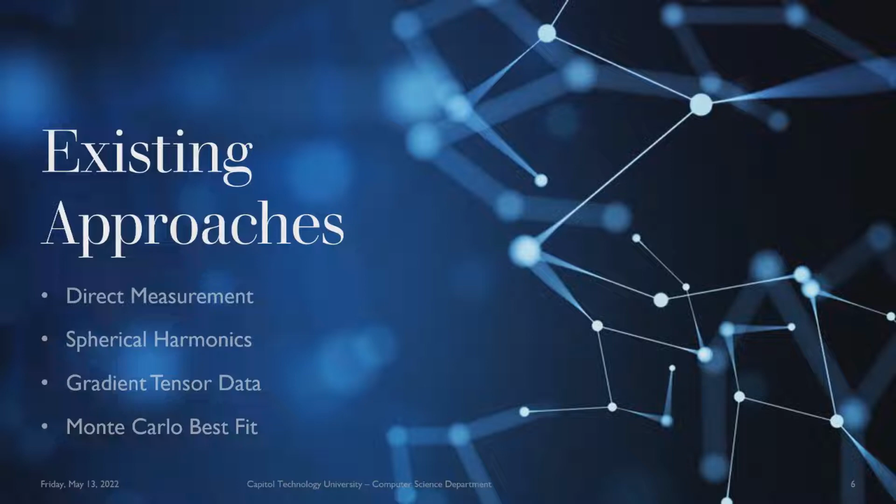In the early 1970s at NASA Goddard Space Flight Center, William Eichhorn developed a method that would attempt to measure the magnetic dipole moment of a spacecraft using spherical harmonic analysis. This method would rotate the test article about the z-axis while recording the B field measured by the magnetometers, placed at specific distances from the spacecraft. The fields would effectively be mapped onto a sphere, and a Fourier transform would be performed on the data. A method similar to this was recently proposed by Louis et al.